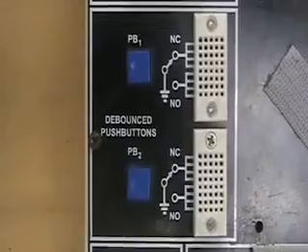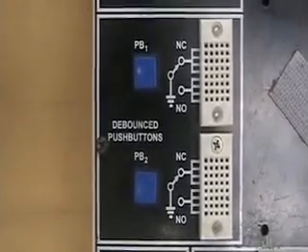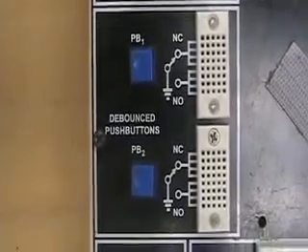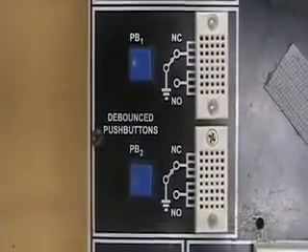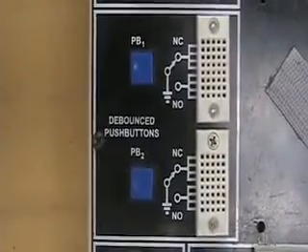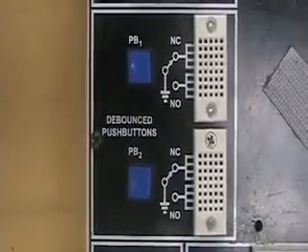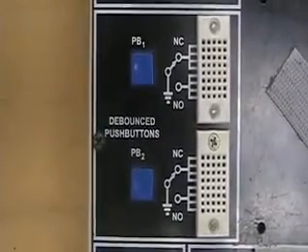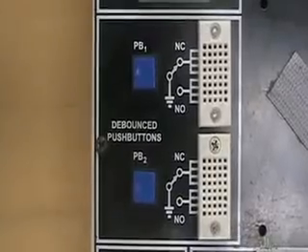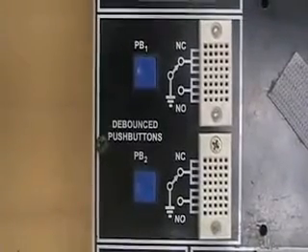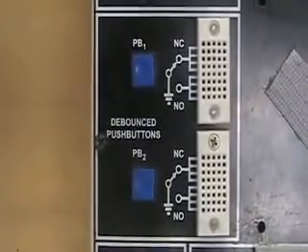In a configuration using the normally closed nodes, the nodes are grounded when the push button is up. When the push button is pressed, the connection to ground is opened. Alternatively, in a configuration using the normally open nodes, the nodes are only grounded when the push button is pressed. At all other times, they remain open from ground. These push buttons are useful for operations such as advancing the logic state of your circuit.